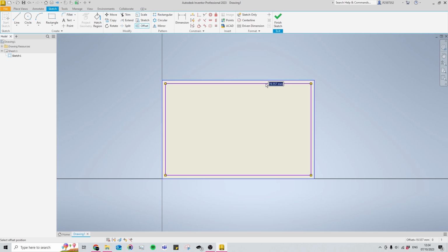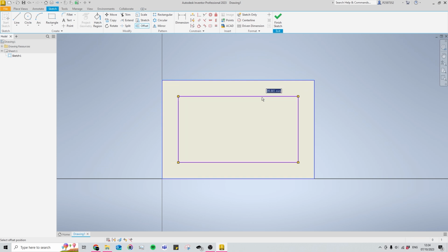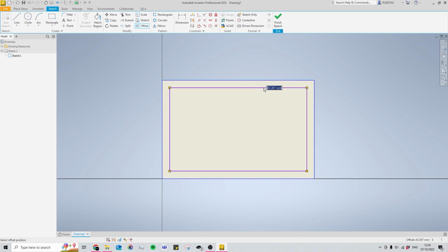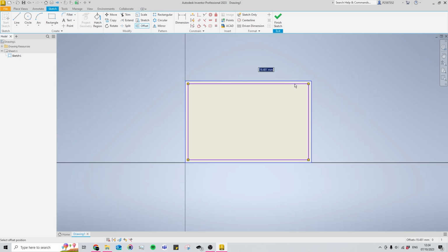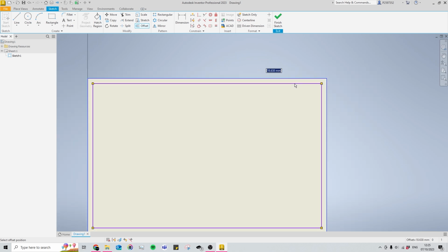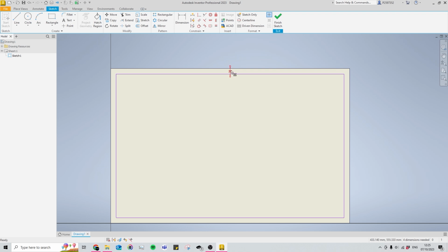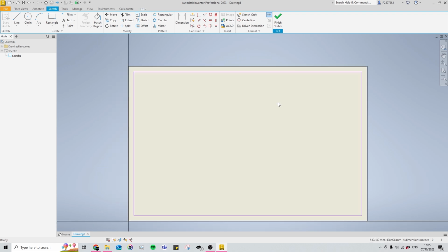When doing this, it's important to keep in mind that the inner space here is where your model views and dimensions are going to be. So allowing lots of room is smart. So here I'd recommend only doing a small border as it leaves us a lot of working space. I'm going to use 20 mil, and now I'm going to delete that dimension. Don't worry about dimensions appearing. After using tools like offset, they'll disappear once you're done designing our border.